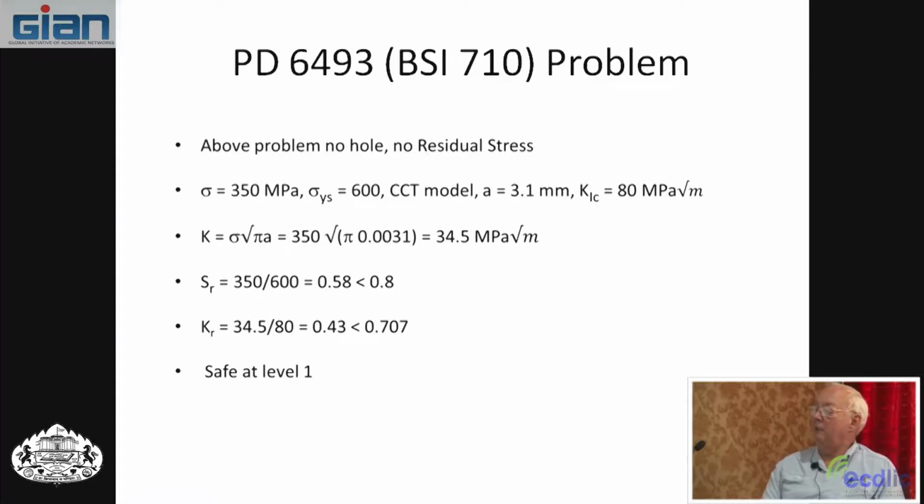So this is MPa. I put this into meters, not millimeters. Again, the problem with millimeters is if you take a square root of 1,000, you don't get a decade. You get 30 something or other. So if you get the wrong units in there, it messes up easily. So here, meters, MPa, so that you get MPa root meters.